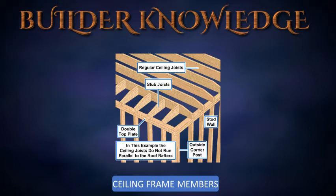Now let's begin with the ceiling framing components, starting with the joists. Joists are the most important framing members of the ceiling. The size, spacing, and direction of travel are given on the floor framing plan. They are usually spaced at 16 inches or 24 inches on center.